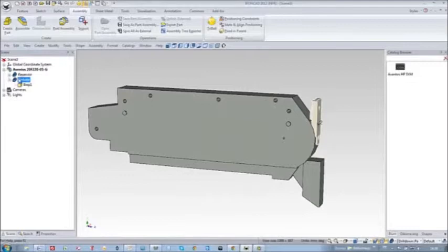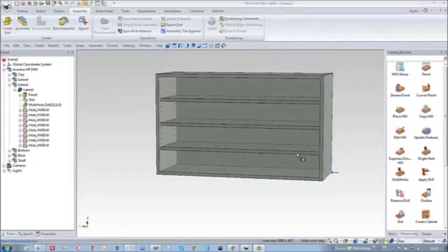Okay, so far it seems to be good, but not yet actually, because I realize that the plate must move forward. According to the documentation, I know that the little extrusion is at 37 millimeters from the front edge of my cabinet. So I first move it backward with the trihedral, and then I move it forward with a value of 37 millimeters. And I'm sure now that it's in the correct position. I can save now my new hardware in my hardware library.